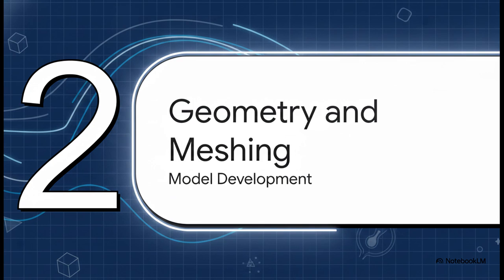Moving right along to Section 2, pre-processing, where we tackle geometry and meshing. This is such a great look at our pre-processing phase in ANSYS Design Modeler. We are comparing the bare geometry of a severe 70% stenosis, which is basically a highly constricted artery, to our finalized structured quadrilateral grid. Notice how beautifully that mesh elegantly conforms right to the narrowing throat. That's crucial because we absolutely need to capture the complex flow behavior exactly where it matters most.